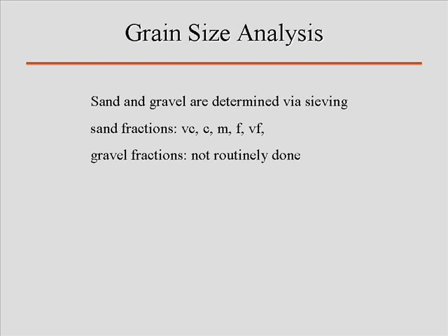Never, ever, ever grind a sample for grain size analysis. Never bake a sediment for grain size analysis, because baking causes the clays to shrink, and you could actually make larger clumps of stuff by doing that. Air drying is always the best thing. And gradual shaking to break the particles up is a good idea. And it's always a good idea to add some sort of a mixture, a soap if you wish, that will promote the breaking up of these clay particles. All that is the preparation stuff that you have to do for grain size analysis. Once you get the particles all busted up, you put them in the columns, and you do your analysis.